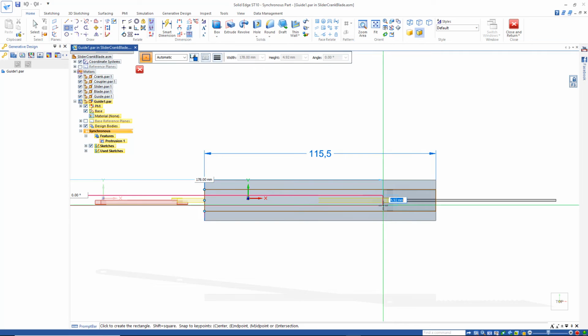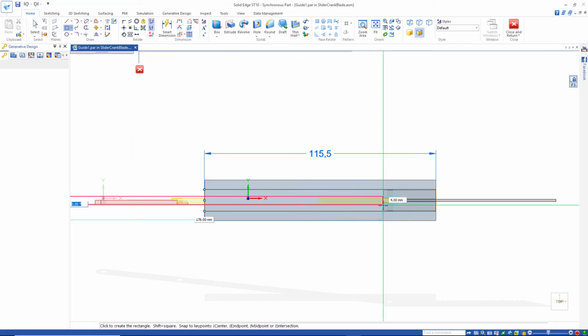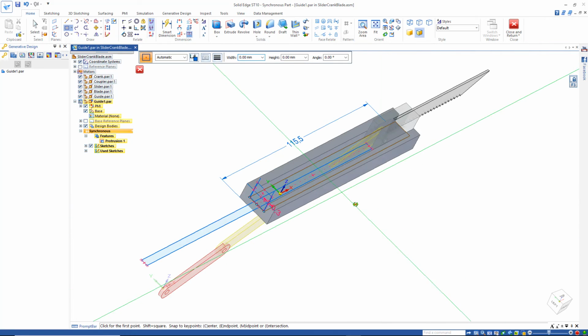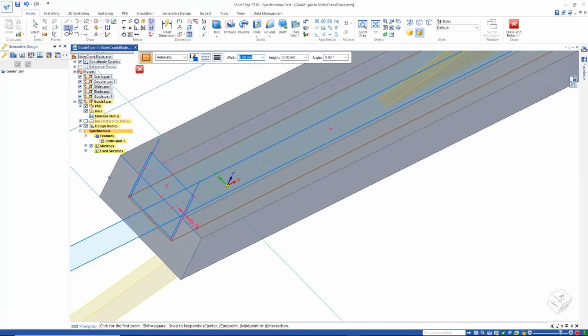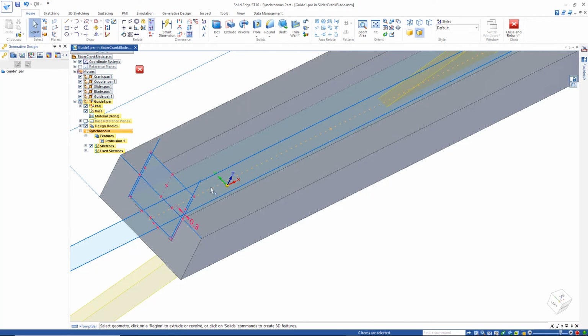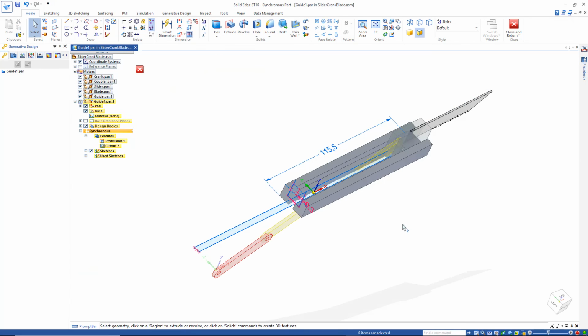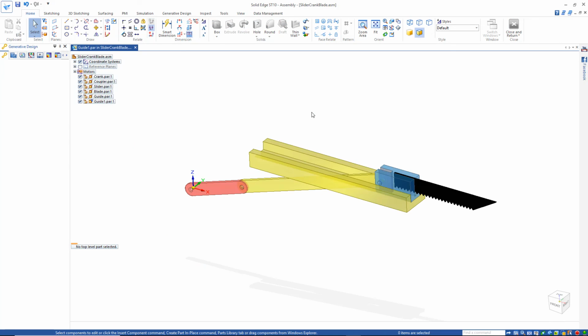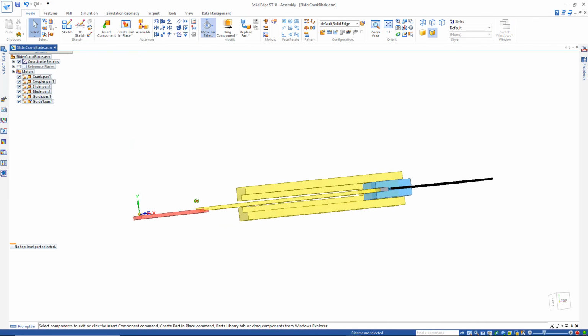178 tab, and I'll make that, say, 4 wide, because I know the part's 2 millimeters wide, and accept that. So then all I need to do is come in and extrude this face right here. Grab the arrow and push that through. So now we've got rid of that interference. So let's close and return. Now you can see there's a channel in there.